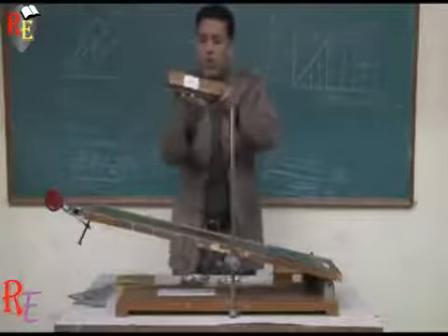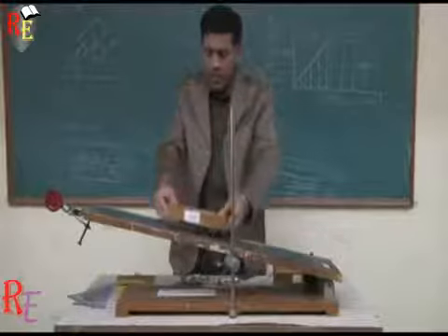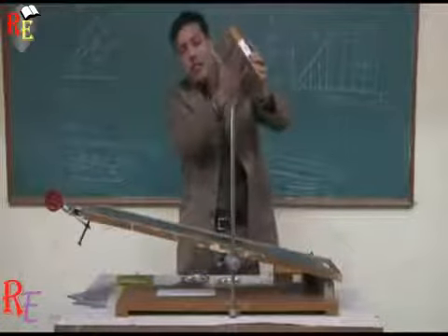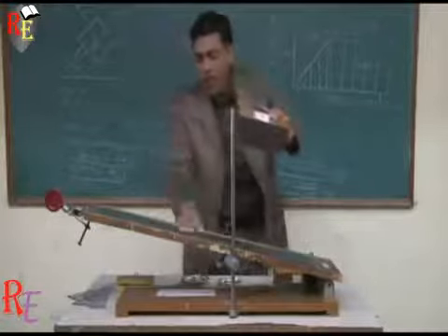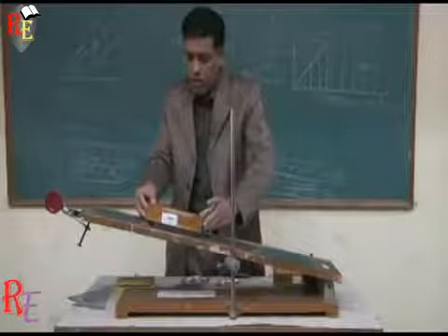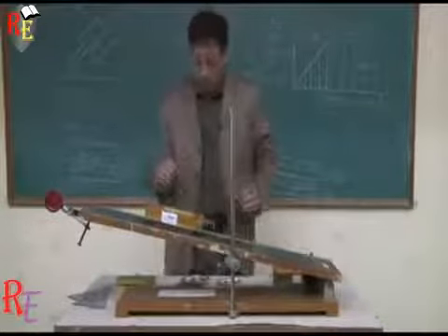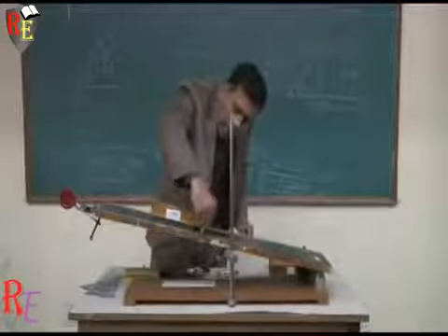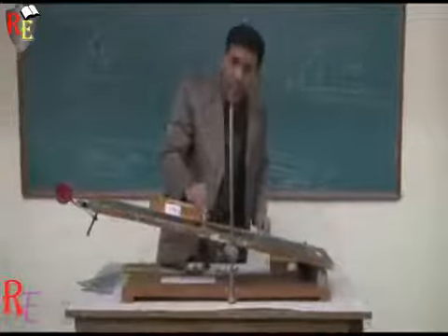I would place the trolley on this incline, and I have to determine the coefficient of static friction between this graphite pad and this stainless steel. I would place it on the incline at any suitable position. Then I would mark a certain reference point on this incline, so that I can visualize the motion.